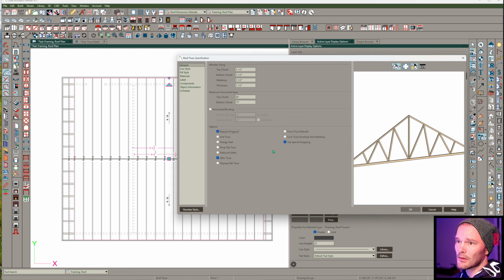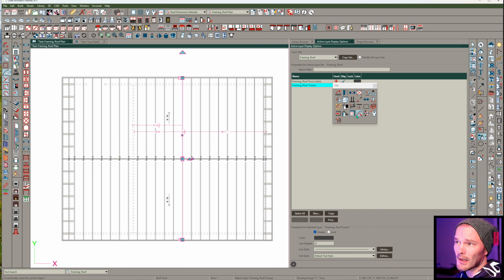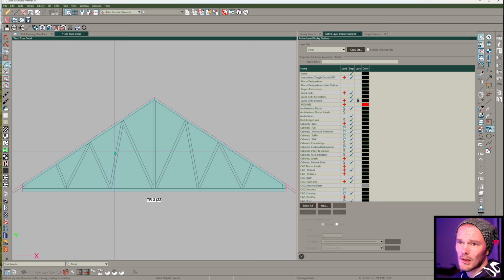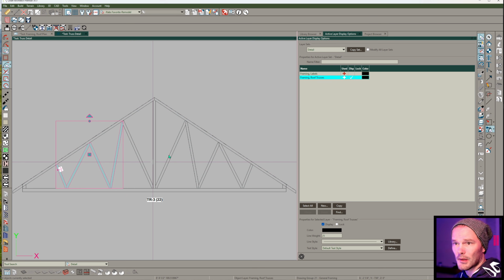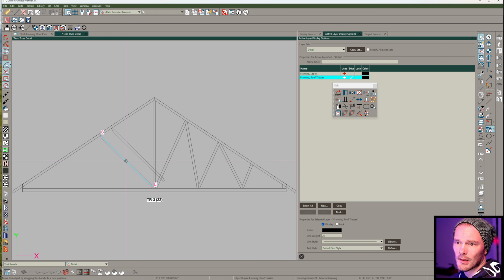Sometimes I'm trying to force a particular truss profile and make like a big decorative truss. This is a really easy way to make a big decorative truss, in case you didn't know this. So you can take all these guys. Let's just get rid of these real quick. And maybe I want to rotate this to be a 45, right? Yeah, something like that. Bam.